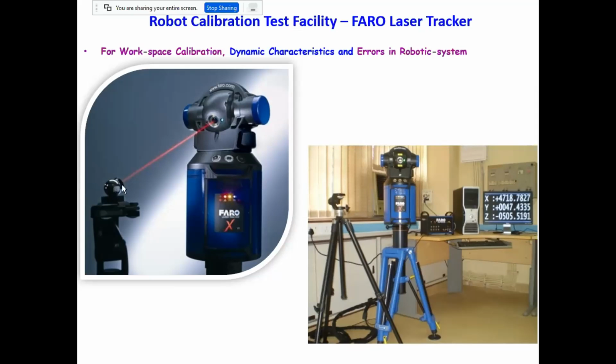This is a retroreflector, which is tracing the path of the laser. You attach this retroreflector to the end effector and move it in any direction. Automatically, you will get all the positions, orientations, velocities, and accelerations in the Dynacal software. You'll see the precision involved in the joint angles and joint positions.